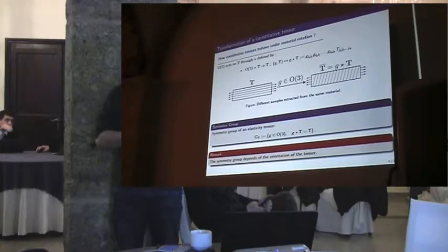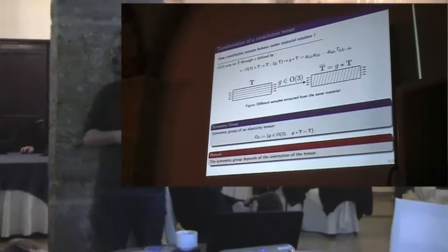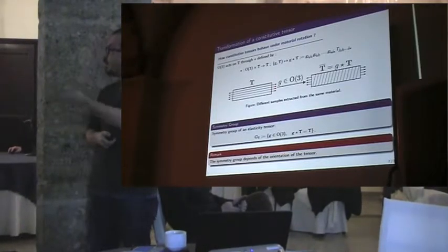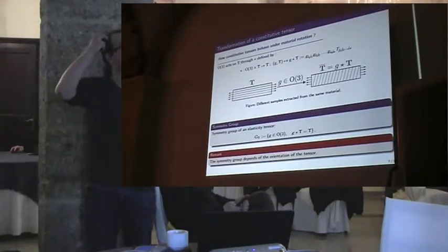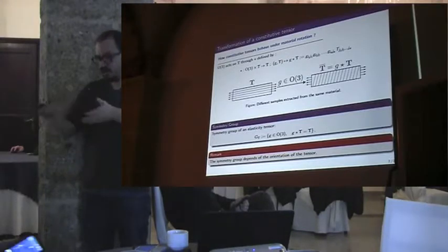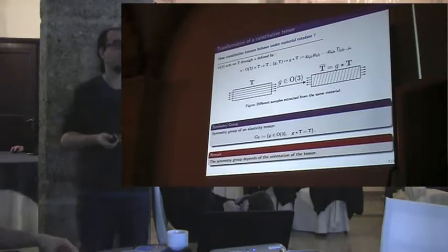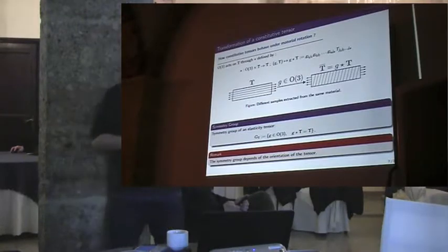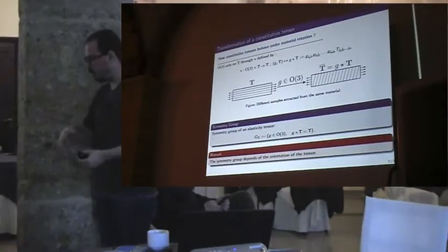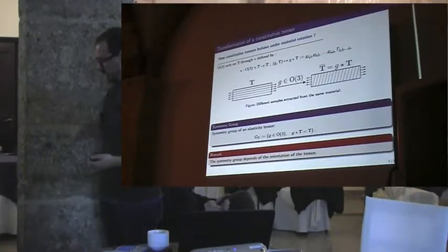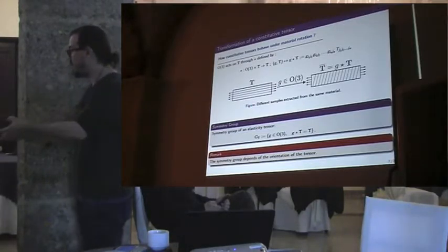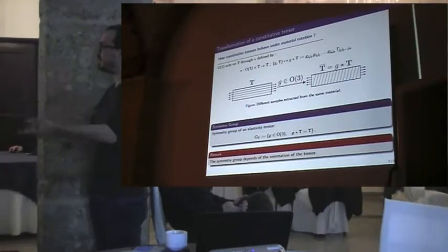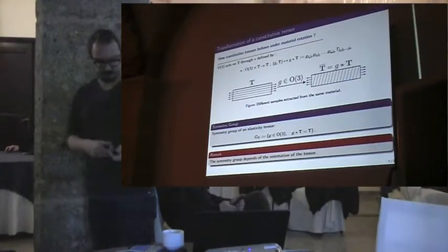If I act on a fourth-order tensor, G will act 4 times on my tensor, and so on, 5 times on a fifth-order tensor, and 6 times on a sixth-order tensor. That is called tensor action, and it's related to the Rayleigh product that we saw yesterday. So as soon as I know how my tensors are transformed under an orthogonal transformation, I can define the notion of symmetry group, which is the set of transformations, I hope non-trivial, that leave my behavior invariant.